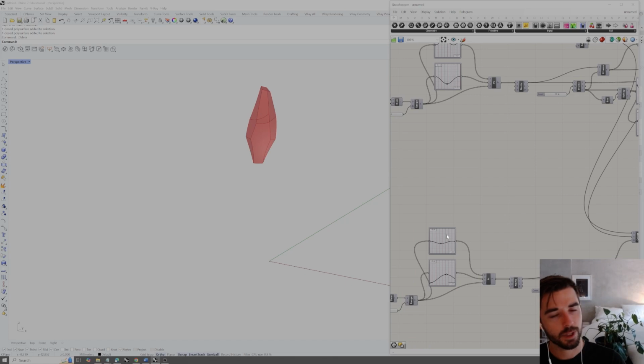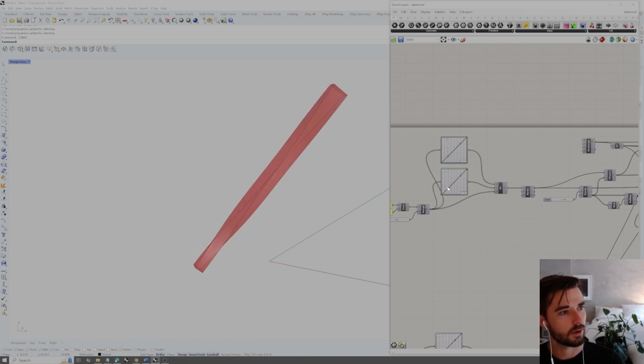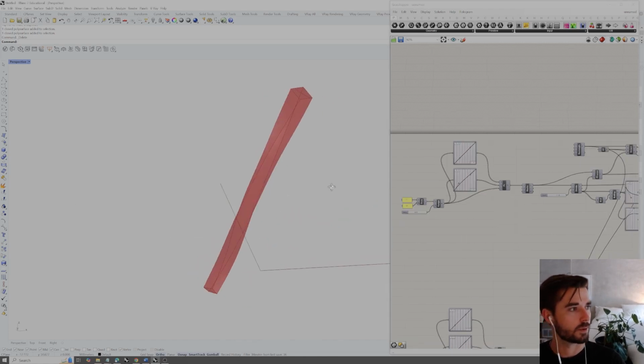If we wanted different control than these sine controls, as I mentioned before, we might want to right-click, go to Graph Type, and select Bezier. So if we select Bezier for all of these, we'll see that the overlap is exactly the curve. So it's a majority overlap here. And this is because our curves are almost identical.